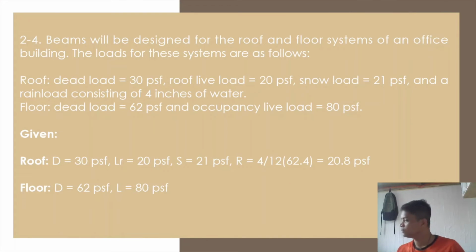Okay. Next question. Number 4 or 2-4. Beams will be designed for the roof and floor system. Meaning, dalawang kon tayo dito. Meron tayong separate sa roof, meron din separate sa floor of an office building. The load for this system are follows. Sa roof, meron tayong dead load of 30 PSF or the pound per square foot. Roof live load 20. Snow load 21 and rain load consisting of 4 inches of water. Floor is dead load 62 pound per square foot and occupancy live load is 80.